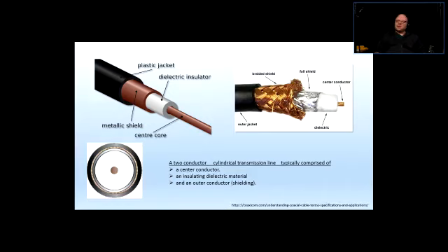Then you can have the internet through the cable, and what that means is the coaxial cable, the concentric cable, this RG, and here it is. Usually to your home or to your business, if it's internet through a cable, it's going to be RG6, and we'll talk about what these are. There are different designations: RG, radio guide, RG6, RG11, RG58, RG59, which would be the most commonly used types as far as consumer and most commercial uses.